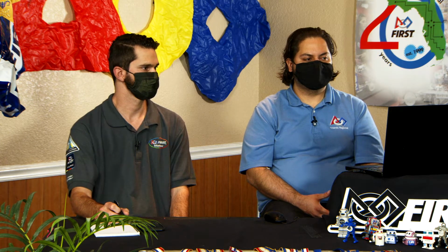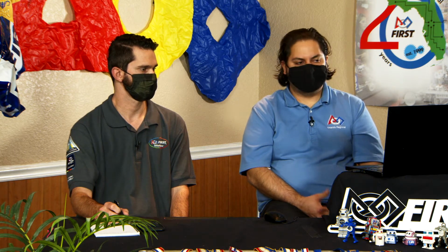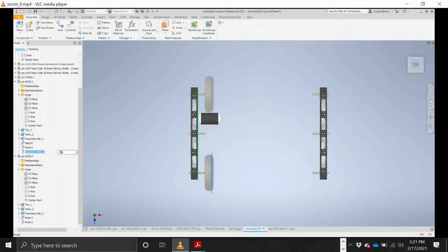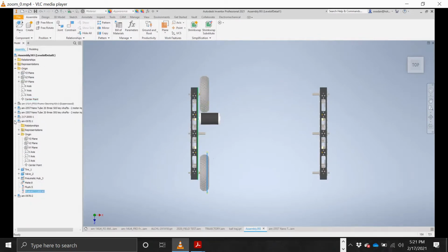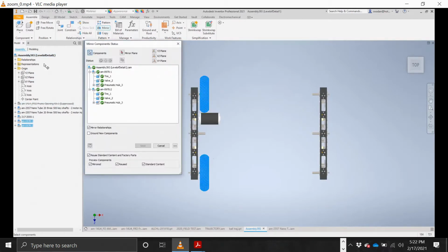You can pull weights off of it, and you can figure out where your center of gravity of your robot's going to be. And figure out how heavy it's going to be, and that's going to be critical. It's critical to figure that out during the design time, instead of waiting till you built a robot and found out that you're 50 pounds over and you're going to have to remove components. So less cheese holes. Yes. At best, cheese holes. At worst, you're going to lose some functionality that you wish you had.